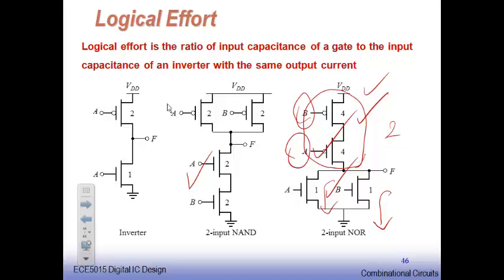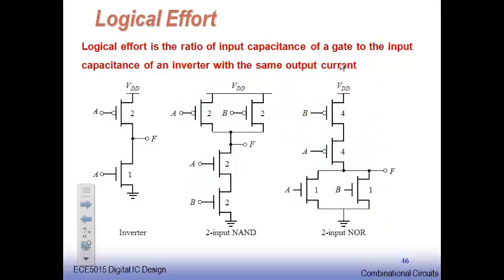Understand it? Whereas here it was what? 4 by 3. And you go for calculating for a 3 input NOR gate. In addition, you will have another transistor here. Then the size will be what? Instead of 4 here, 3 devices.